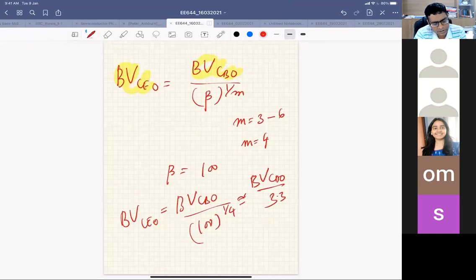Okay. When we're using a BJT as a switch, it operates in the saturation mode. That means you're injecting electrons from both sides, so both junctions are forward biased. When the transistor is off, the emitter-base junction and collector-base junction are not forward biased. The moment both junctions are forward biased, you're injecting more electrons.